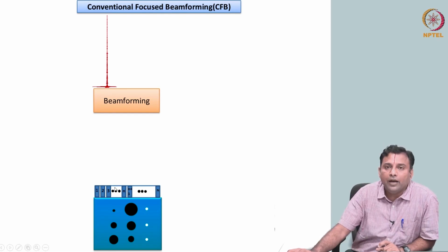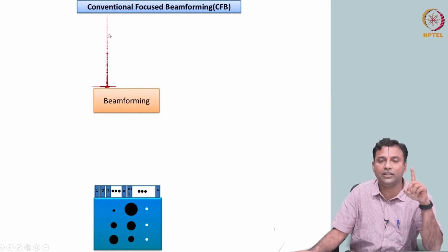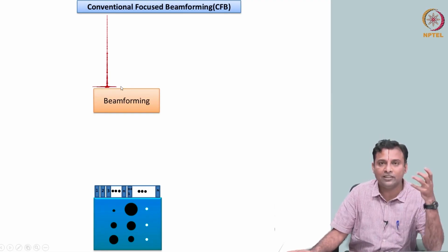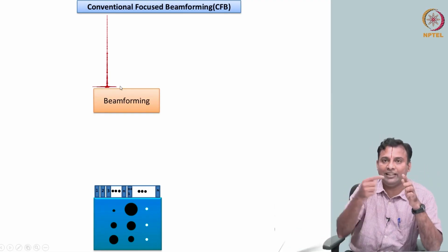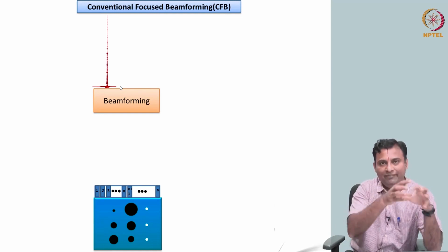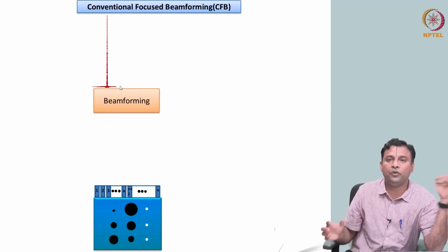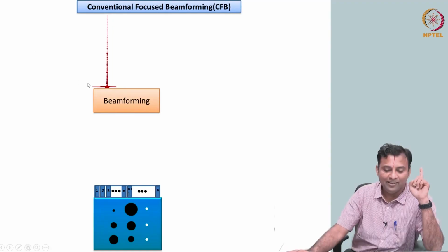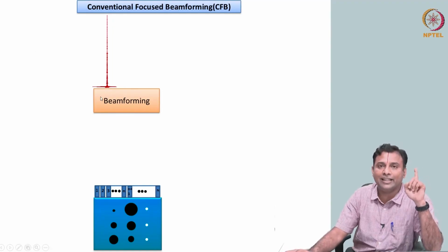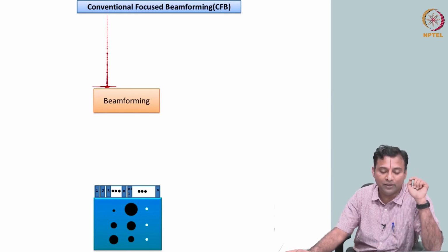This is just one A line. If you had a single transducer element, this is exactly what we got. This all happened, we didn't have control. Anything that falls on the surface was summed and what you received was only one line. Here we are doing it explicitly, the only thing is we are able to compensate for the time delay because each one has a separate control.